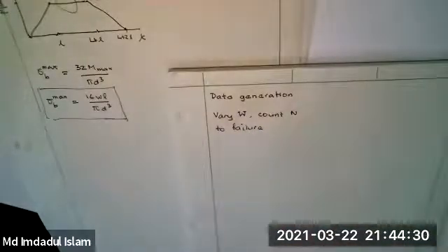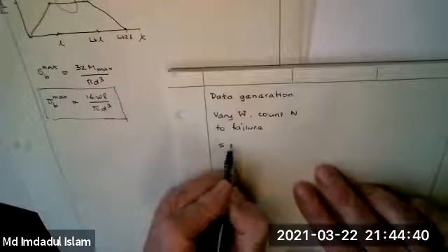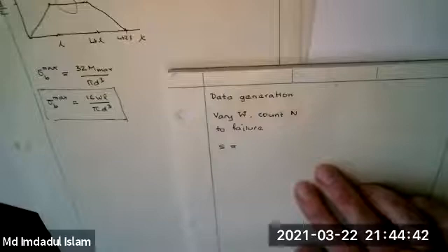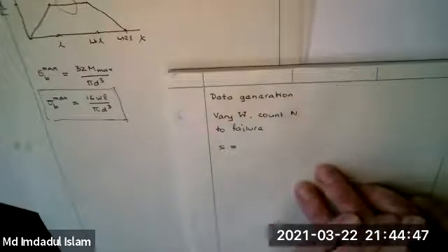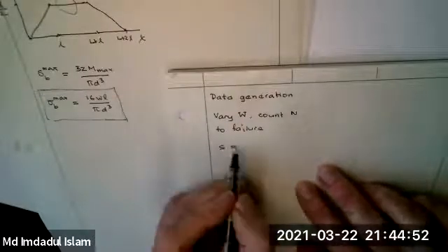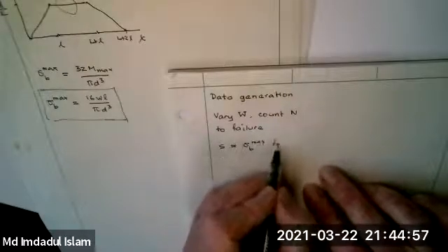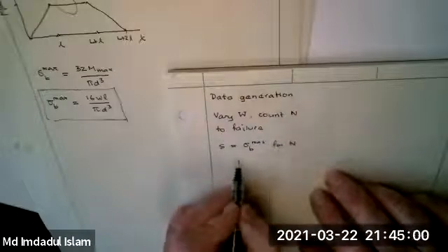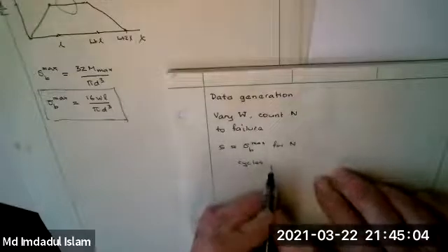Once we've got a certain N, then the stress, the maximum bending stress that produces that failure, becomes the strength. We're going to denote that by S. We use S for strengths as opposed to sigma for stresses. So S is, and throughout this course, S is always measured stresses when something happens. In this case, it's going to be sigma B max for N cycles, with a given material.